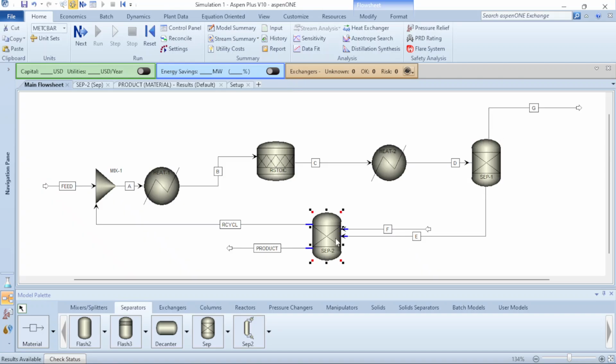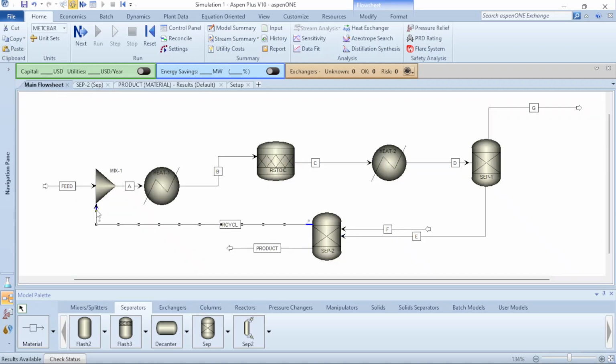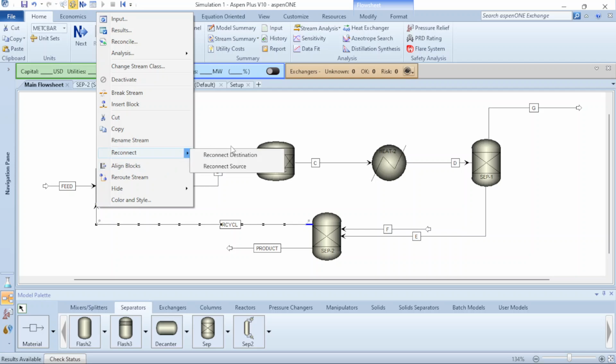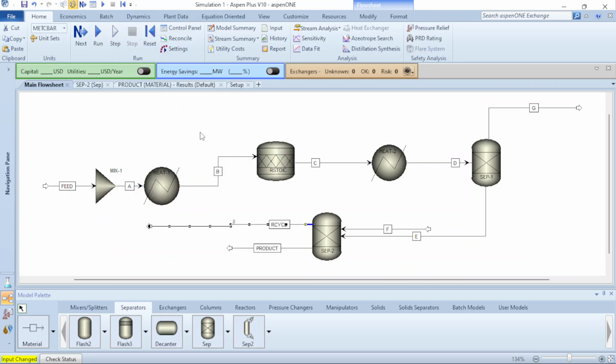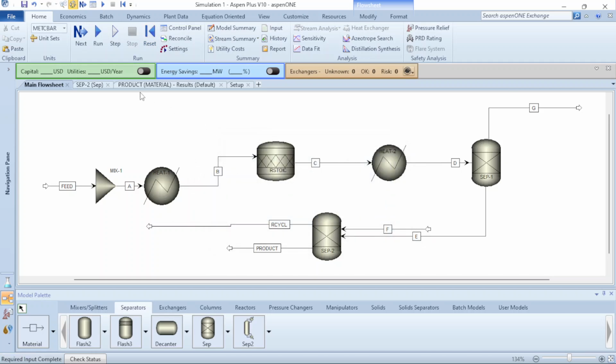The same thing applies to this side. So for here, what I did was I just specify I needed to take heptane from the mixture of toluene and benzene. So just select that, and that will pass through the recycle stream. The outlet stream that I wanted to pass is this one. So whilst doing it, don't just connect this one for the first time. Wait. Make it be a tear stream like this, a stream that's not attached. It's not a recycle. Then let me reinitialize and run.